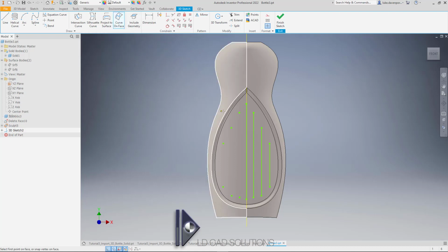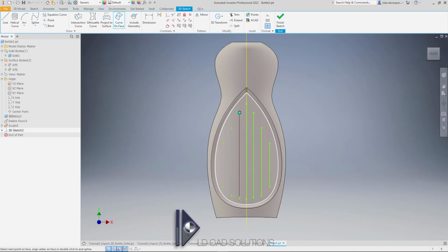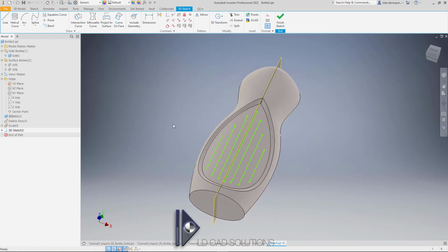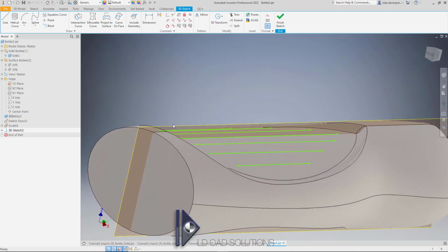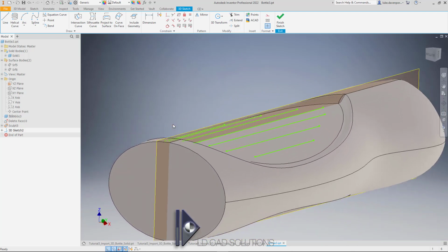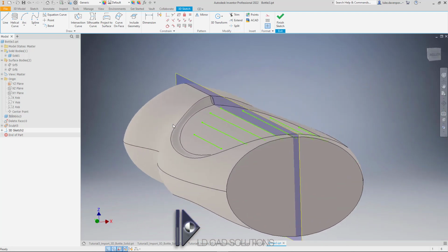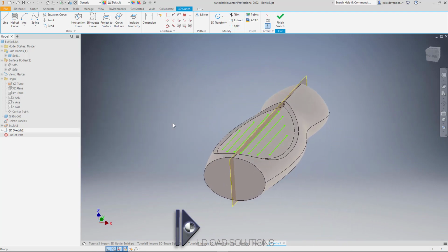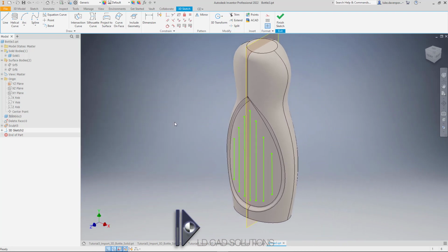And then I have to draw the curves again. I can't actually mirror the curves in this case, but let's say OK. Spacebar to repeat. Spacebar to repeat. Okay, so let's take a look at that geometry. If I spin this round, you see those curves are on the face itself. So that's probably quite a good set of construction geometry to use as a guide for my new surface.